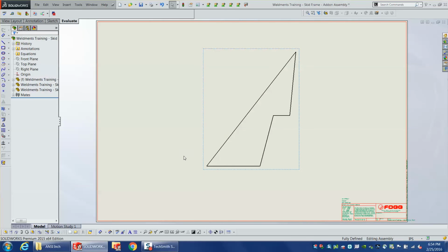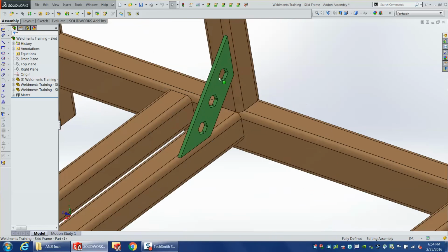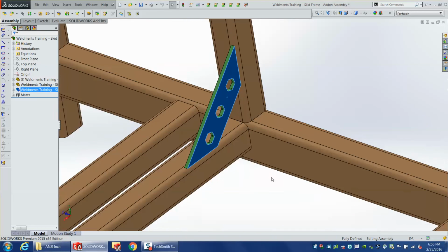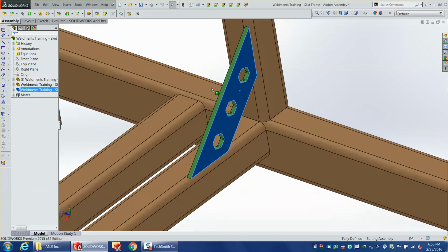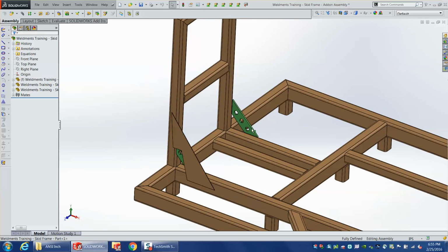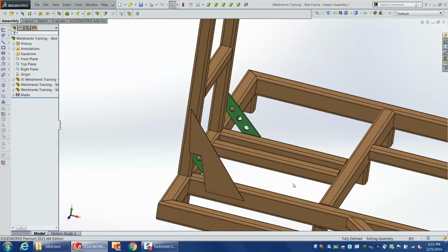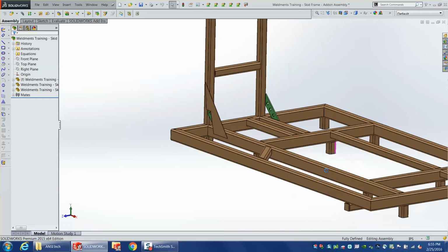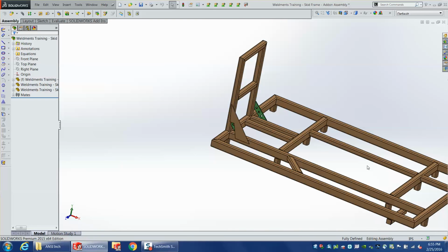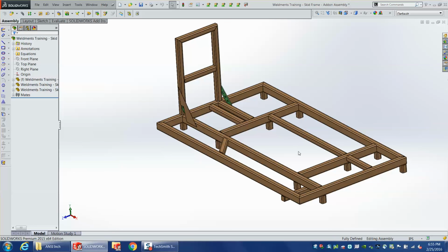So he's saying that rather than the method I used here of adding something as a part at the assembly level for add-ons, because I wanted to be able to process that as a separate part, you could also make a custom profile for it with the part number built into that description and pull that through your weldment cut list. So whichever works better for your organization, the way that you want to process things.